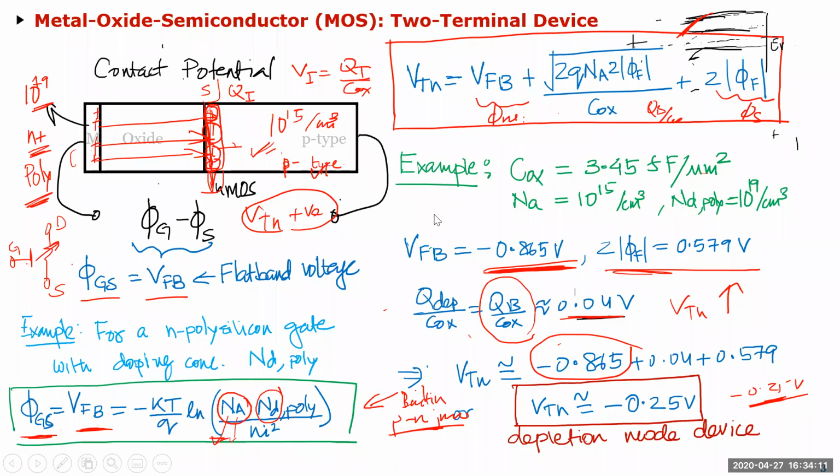Yeah. Go ahead. That's maximum because after inversion, when it is converted to N type, when we are increasing the gate voltage, the electron concentration is also increasing on the surface. But in the linear region, when the inversion is occurring and after VD equals VD saturation, we are having a pinch off voltage and the depletion layer isn't increasing near D.